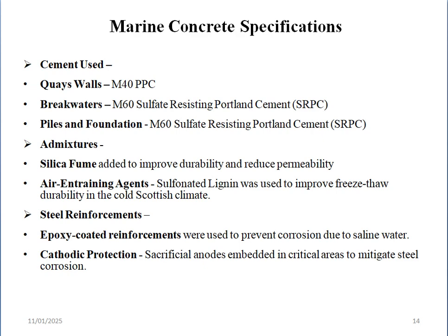Marine concrete specifications. The cement used was as follows: quay walls M40 PPC was used, breakwaters M60 sulfate resisting Portland cement or SRPC was used, piles and foundations M60 sulfate resisting Portland cement was used. Admixtures: silica fume was added to improve durability and reduce permeability. Air entraining agents. Sulfonated lignin was used to improve freeze thaw durability in the cold Scottish climate.